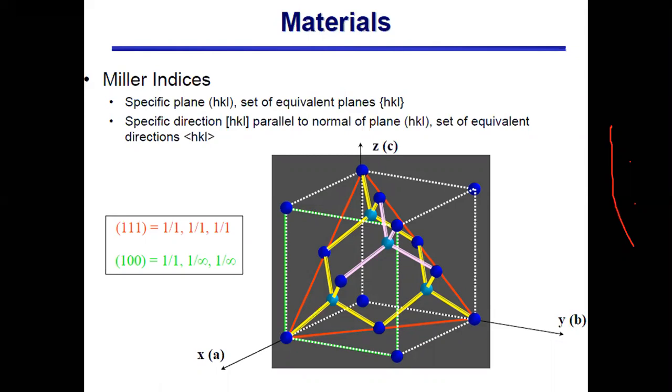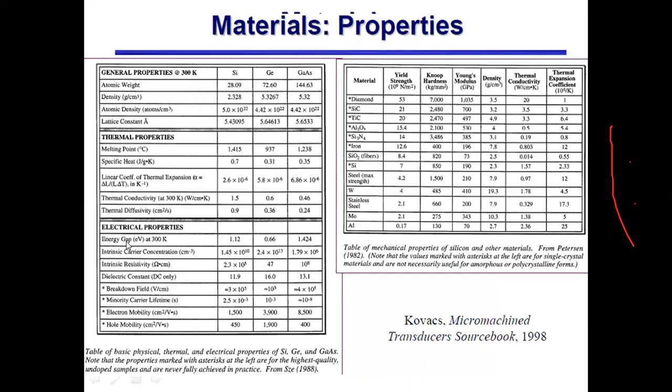of the silicon wafer. So normally when we buy silicon wafers, the first question that we ask is whether it is single crystal silicon or polysilicon. If it is a single crystal silicon wafer, then we have to ask what is the plane on the top surface of the silicon wafer, whether it is 1, 0, 0, 1, 1, 1, or 1, 1, 0, etc. Because that is normally important when we are doing bulk micromachining.